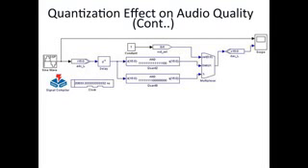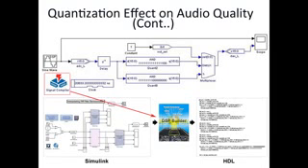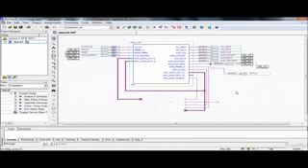With DSP Builder, it allows you to go from system definition and simulation to the system implementation. The DSP Builder signal compiler block reads Simulink model files that are built using DSP Builder and MegaCore blocks and generates the hardware description language files for synthesis, hardware implementation, and simulations. Now we are going to import the DSP Builder model into the Courseware project.